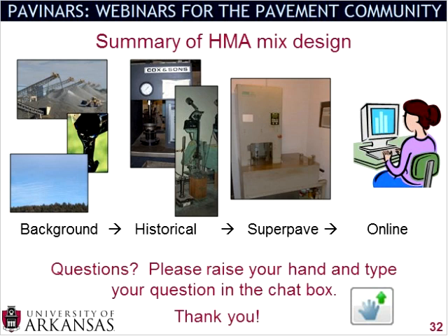And you say mechanistic-empirical HMA design, and this is kind of a hot term right now because of the mechanistic-empirical design guide. That guide looks at pavement structures, and the important thing is that as loads go over the top of your pavement, there are stresses and strains throughout your pavement layers.